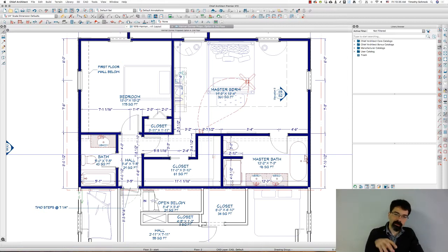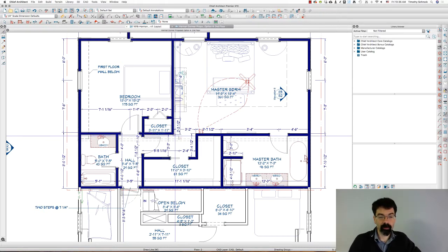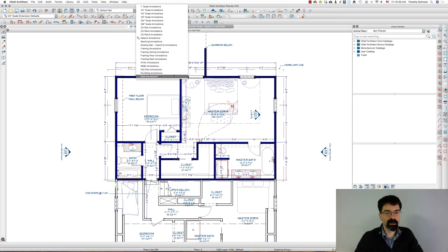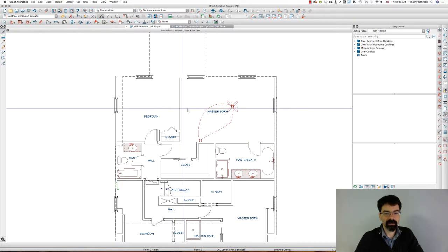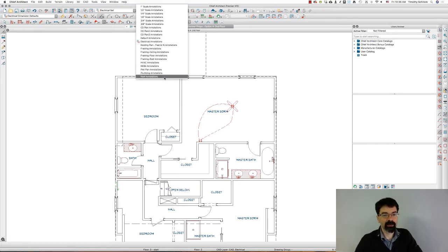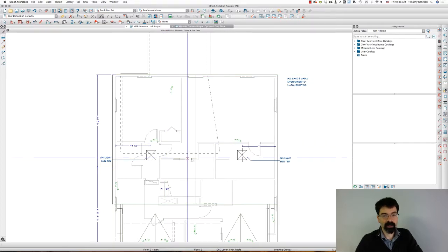Because I see it as part of the roof system, I put it on that roof planes layer. And now anytime I turn it on, turn it off, change, now if I change line weight or color or line type in a layer set, the polyline will not change because that's not set as by layer. But I really don't care about that part. If I go to electrical, obviously I'm not going to see roof planes. I'm not going to see that line in this layer set. But when I go to my roof plan, that's where it's going to be.